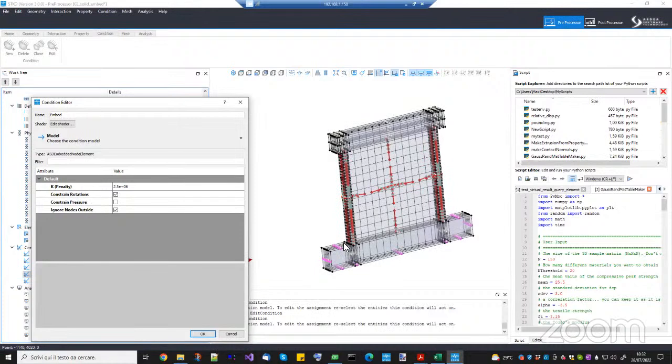Okay, can the concrete model consider this? Well, it's not the concrete itself. I mean, the pinching effect that you see in material models such as, for example, Pinching4 in OpenSees, they are phenomenological models. Actually, the pinching will be automatically visible as a combination of the crack opening in shear in concrete with the plasticity of the rebars, okay?